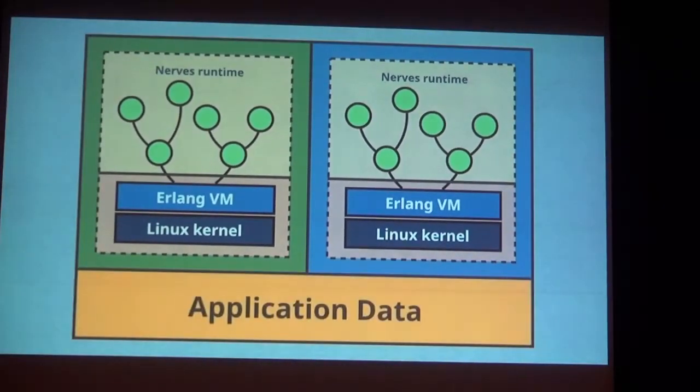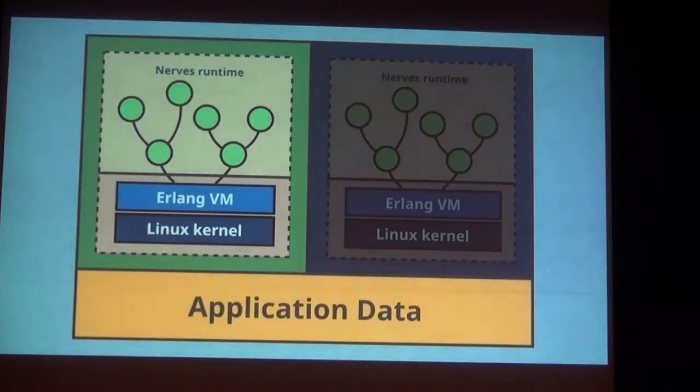Then, we also give you a location to put your data. And when you update, you will have one that is active and one that is inactive. When a firmware update comes into the inactive slot, you can try that firmware. And if it doesn't work, you can fail back. It's safe.